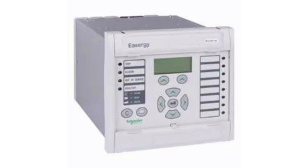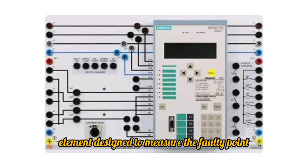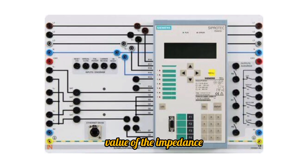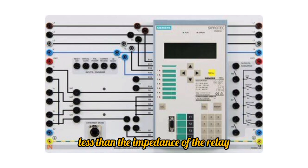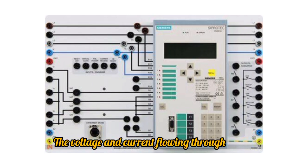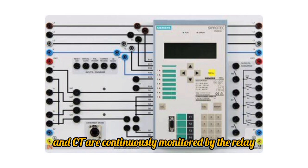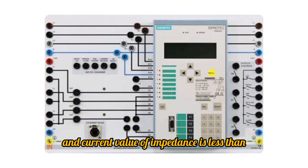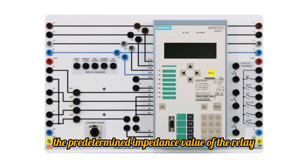Distance relay theory. The distance relay is a distance protection element designed to measure the faulty point. The operation of this relay depends on the value of the impedance. It trips the circuit breaker and closes the contacts when the impedance of the faulty point is less than the impedance of the relay. The voltage and current flowing through the PT and CT are continuously monitored by the relay and it starts operating only when the ratio of voltage and current, the value of impedance, is less than the predetermined impedance value of the relay.